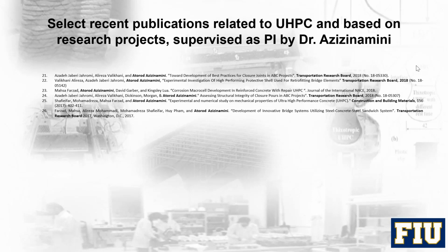Yeah, we've done a good bit of work on overlays. We're promoting that through the Every Day Counts initiative. States around the country are trying this out. So yes, it can be used as a riding surface. The primary purpose is to rehabilitate deteriorated bridge decks. So you take off 1.5 inches or so of your old bridge deck and the contaminated concrete in that 1.5 inches, and you put back what you might call an armoring layer of UHPC, and it armors it. It provides you a very good riding surface, but it also protects the deck, so you get a good long service life.